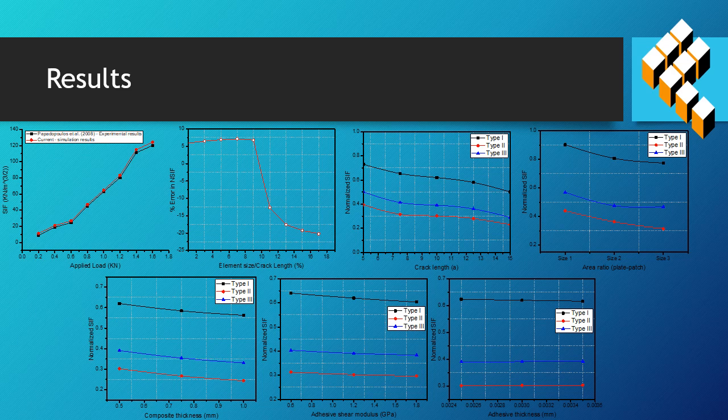Additionally, we have also considered a mesh independence study, because whenever the mesh changes, obviously the results will change. So in this condition, we noted how fine a mesh can be used for the current work, which has a very close result with the experimental work. And when the results were far away from the original results, then we stopped the mesh size. Later on, once the finite element results were verified, a further parametric study was conducted through the finite element method.